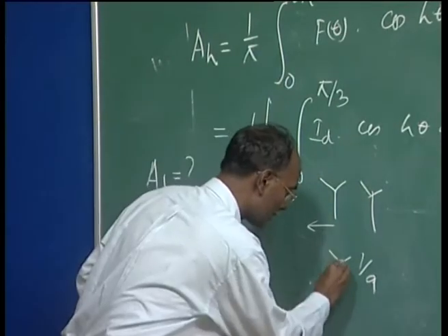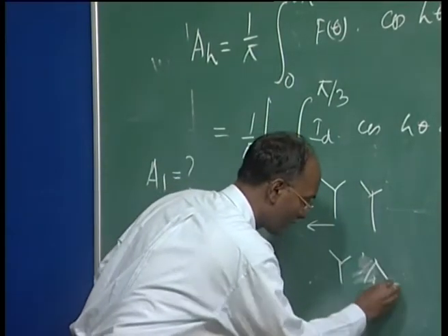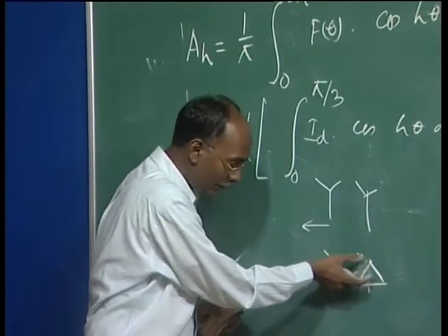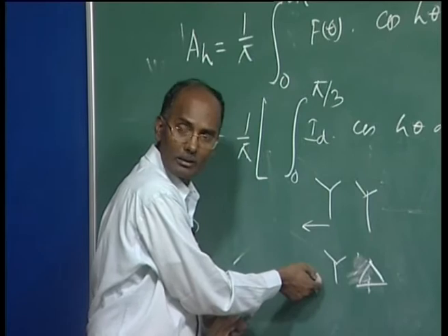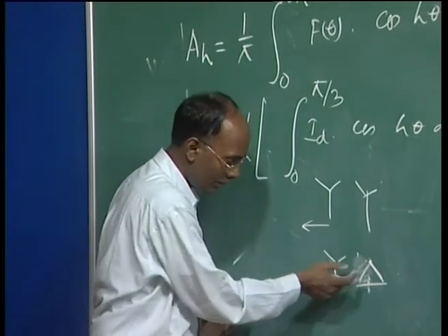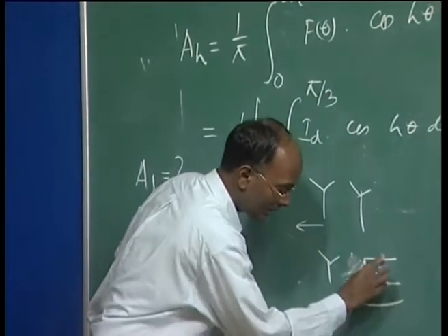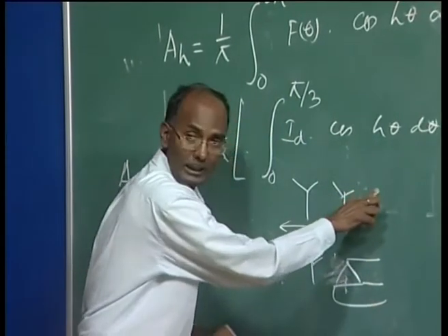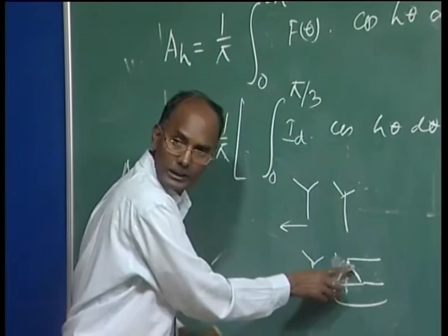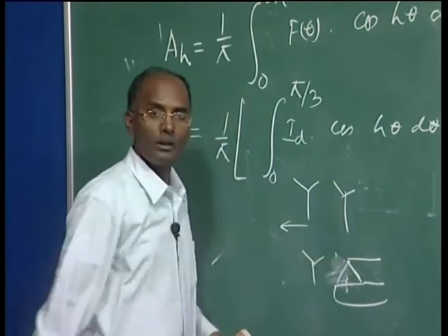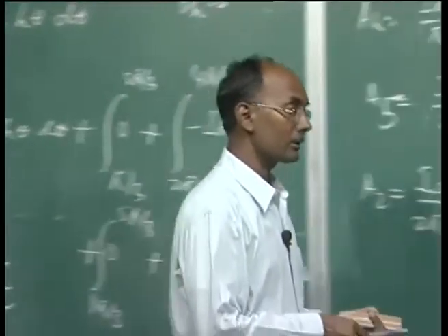But if you go for star delta, we go for the phase current here, and that phase current becomes the line current here. So here this component is different from what we get here, because inside the phases it is different: this minus this current is the line current, which I just showed you in this figure.